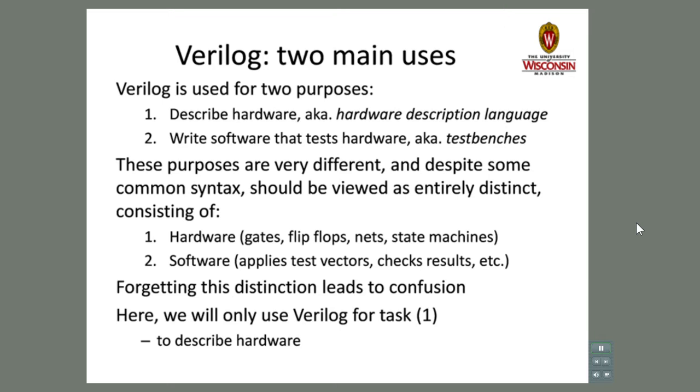This is true, but in my view, it is more helpful to break things between hardware and software, and to then remember that the non-synthesizable features of Verilog should only be used in test benches, which are software, and not in the hardware descriptions themselves. In this lecture, we will focus strictly on Purpose 1, which is describing hardware, and will not introduce or explain any Verilog features that are used solely for Purpose 2, software that tests hardware in simulation.